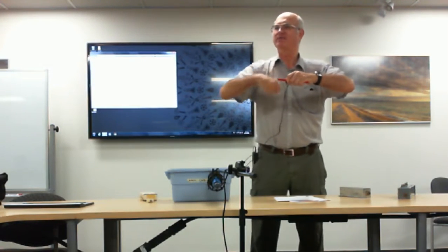Yeah, take one of these guys, cut it to about 2 inches in length, maybe 3, depending on what you want, and just wrap your speaker lead around it, tape it on 2 sides, and you've just made your own choke coil. And in most cases, this will take care of most radio frequency interference for telephones, as well as the speaker systems. In a lot of cases, that's all it takes.